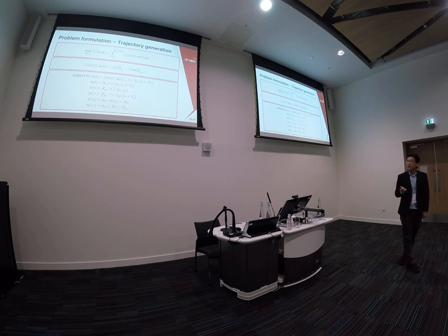Subject to the aircraft dynamics, input constraint, state constraint, boundary initial state constraint and input constraint. These conditions are based on the steady level flight of the kite at the beginning. And the final state constraint. Notice that here we have two different state constraints for the state, and I will explain them later.